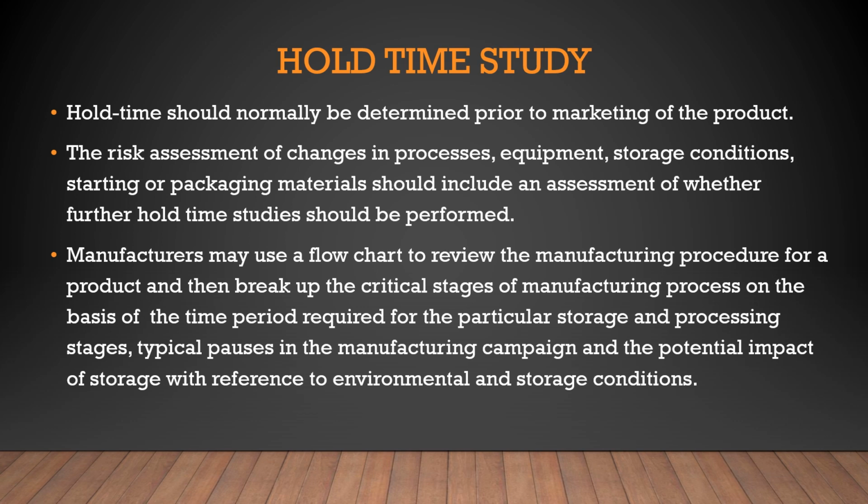Manufacturers may use a flowchart to review the manufacturing procedure for a product and then break up the critical stages of the manufacturing process on the basis of the time period required for the particular storage and processing stages, typical pauses in the manufacturing campaign, and the potential impact of storage with reference to environmental and storage conditions. So how should a hold time study be conducted? Whoever the manufacturer is, the manufacturer has to go with the flowchart so that whatever manufacturing procedure is being used has to be broken down